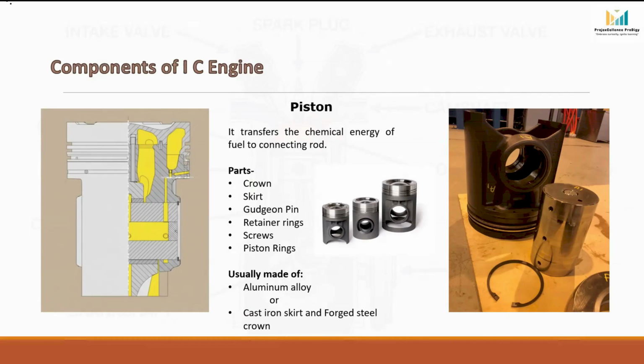In heavy-duty engines, the piston contains internal cooling spaces or cooling galleries. Lube oil is directed through these galleries to remove heat from the piston crown. This helps prevent overheating and increases piston life.